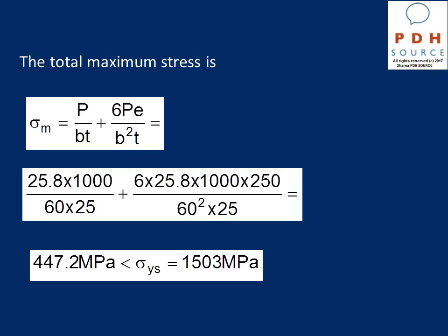However, because of the presence of the crack, the maximum stresses on this tool were limited to this value. So if the stresses exceed 447 megapascal, the tool will fail in a brittle fracture mode. This is what we need to understand, and the example illustrates how the presence of a small notch in a structural element can limit its capabilities to sustain loads.